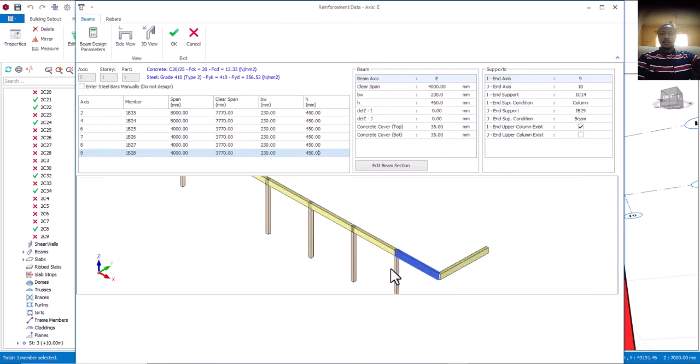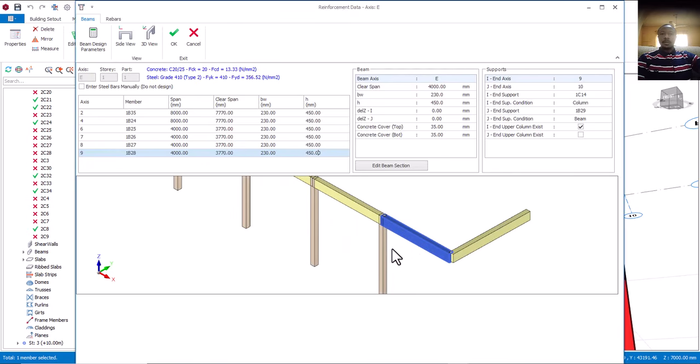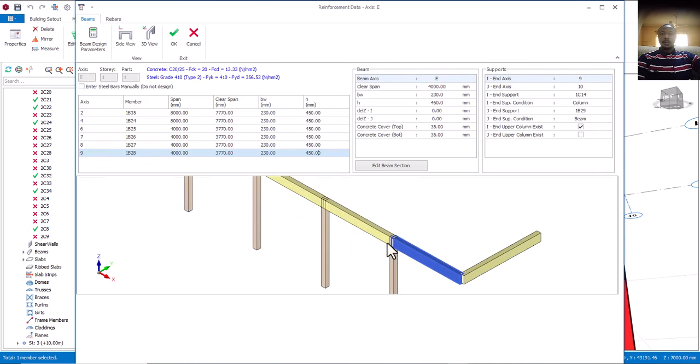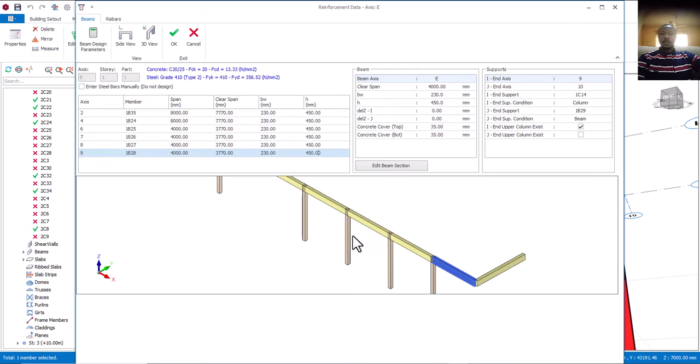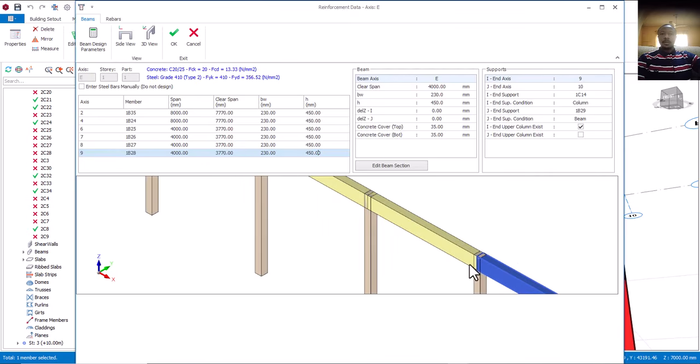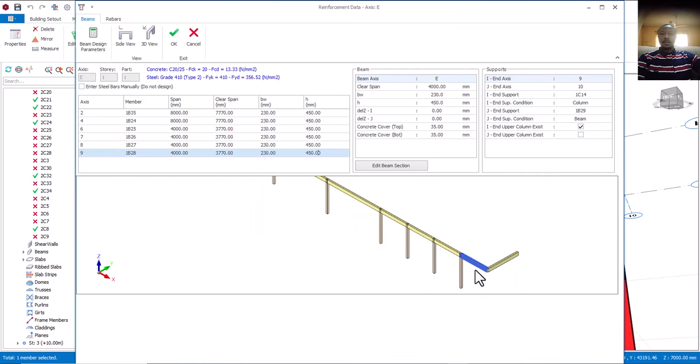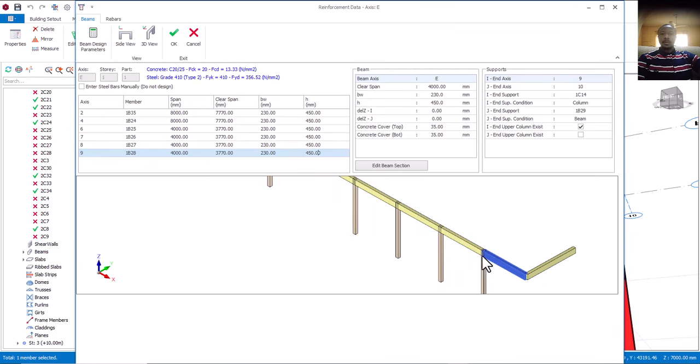Now, if I'm increasing it, the principle is I can't be increasing only this edge here. No, the strength of this beam lies from inside. As the same size is coming from inside, the strength increases. So increasing only this one is not advisable and it's not correct, because this beam is coming from inside. It's supposed to have a drop back. Though it's having a drop back, the drop back is not the same weight. So as I'm increasing this one, I'm going to be increasing this one also, at least the minimum of this. If not, I'll take it from here.